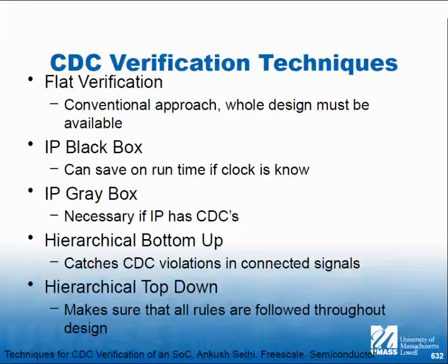I think of the bottom up method as looking at the outputs of a block on a given clock, and then the inputs of the other clock domain, and actually going signal by signal, making sure that designers are doing what the guidelines say.